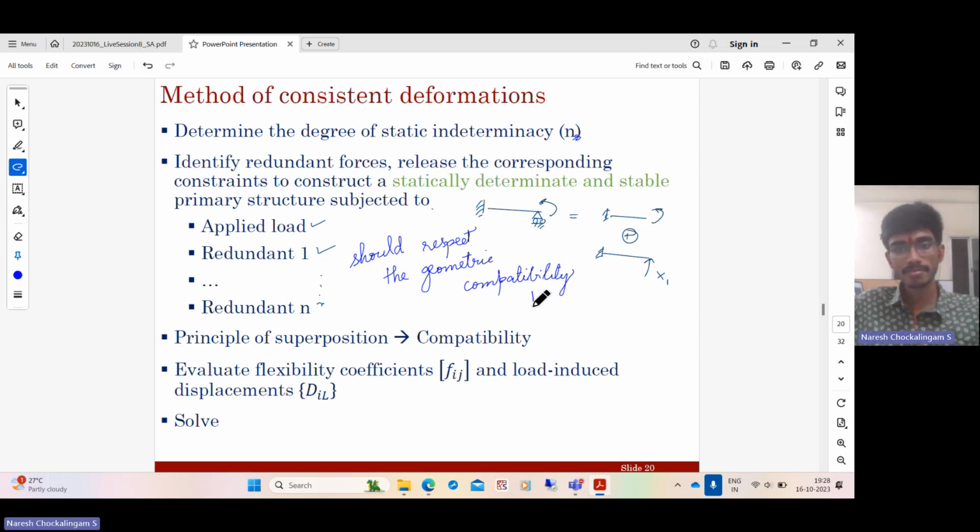So if there are ns unnecessary geometrical constraints, they will correspond to ns redundant forces. Therefore, by enforcing the ns geometrical compatibility constraints, you get a system of ns cross ns equations, where the primary unknowns are forces, and on the right-hand side we have some displacements.